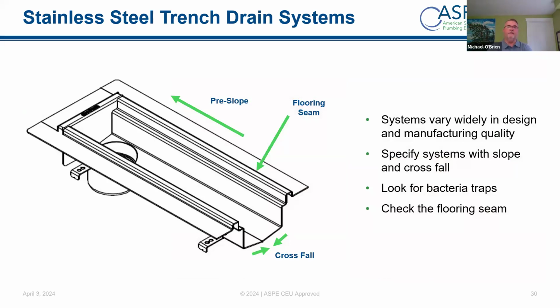You want to have them flush. You want to have them designed to lock into the floor properly. You want to see how they connect to the floor. It's very important. If you walk into a lot of facilities and look at the drains, like I do everywhere I go, quite often you'll see a separation from the flooring material in the drain where water is getting underneath.